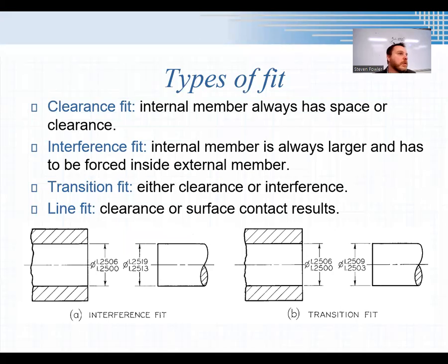Which one do you need? Well, it depends on what we're building. In this case, the perfect example where I need an interference fit. If I want, for example, this to be able to rotate freely, to just put it on there and spin it, that would be an example where I'd want a clearance fit. I don't want the two surfaces to actually touch. I want them to be able to rotate freely inside each other.